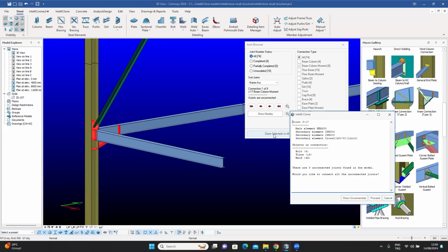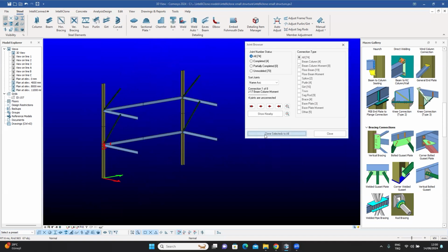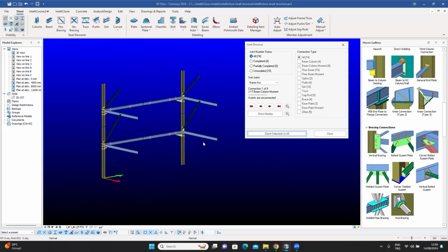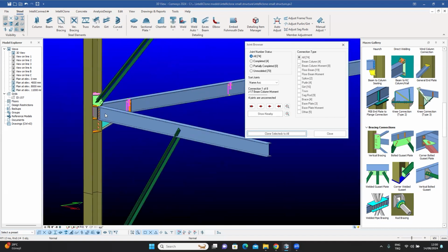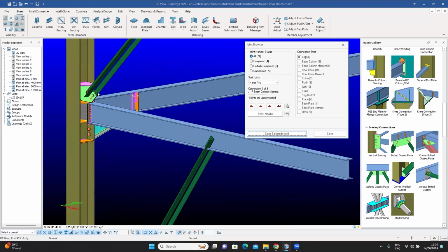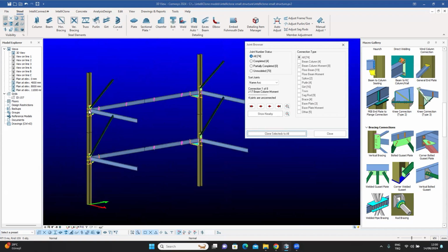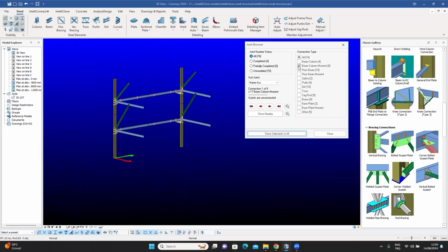And I pressed my clone button, or rather, let me zoom out a bit and then press it, and just press proceed. And when I do that, my connection, that complicated connection which you just saw, is created not only over here, but also at this target with the slightly different angle coming in. And I'm allowing this because I know that the macro will handle that situation. So all my cases are, so let's do another difficult case.